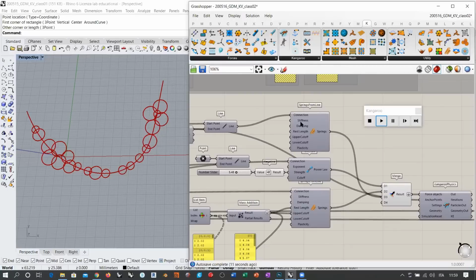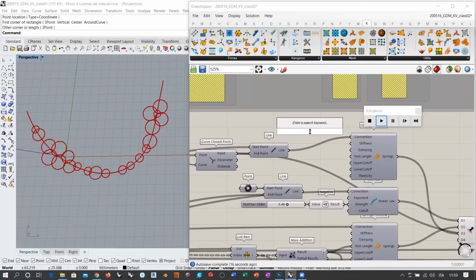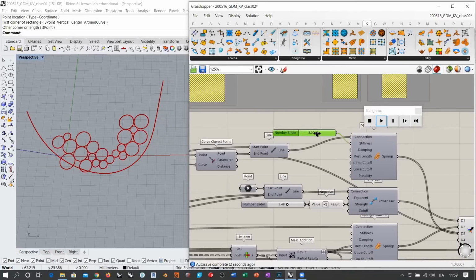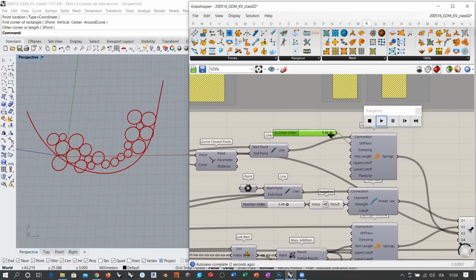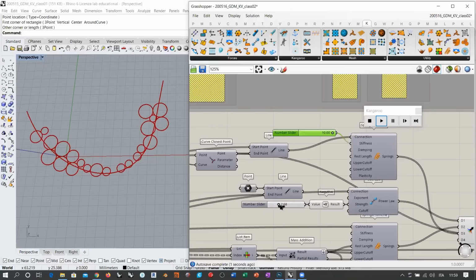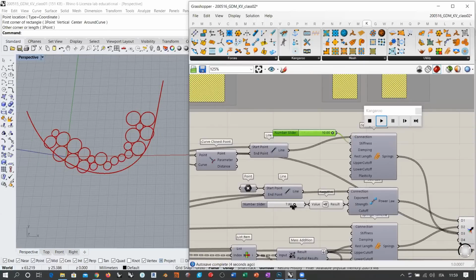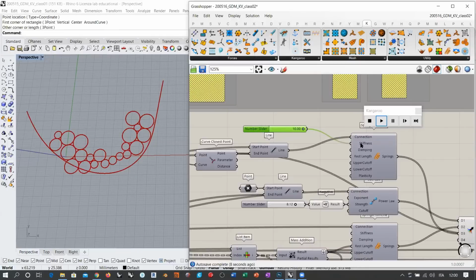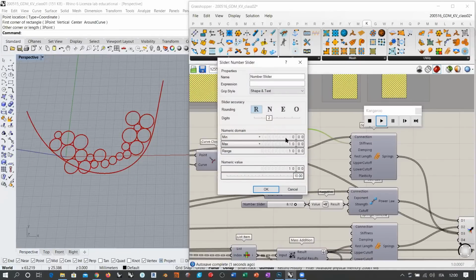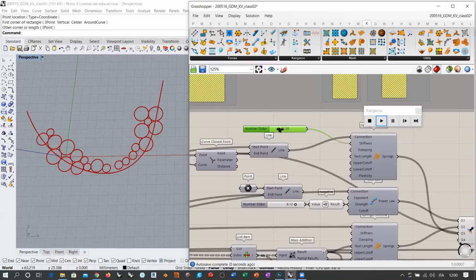Now, this is extremely powerful, because stiffness for the spring from line is set to 1000. Okay, so if I take a slider here like 5.00, you see that these springs become weaker, and you have the possibility to balance this power law. So power law is more effective when this is higher, and you have this. This is basically setting the springs to become more rigidly zero length, so they work better when this value increases. And so you find the balance between these two values here, which depends on many aspects.